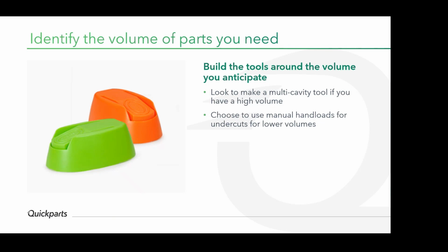Of course, a little bit later, when you need higher volumes, the tool is made accordingly, right? So you may have a multi-cavity tool, hardened inserts, so that you can make a large volume of parts off of that tool, and it's more cost effective, right? So just make sure you identify your need for that particular tool construction. Prototype or production, just identify that and make your tool accordingly.